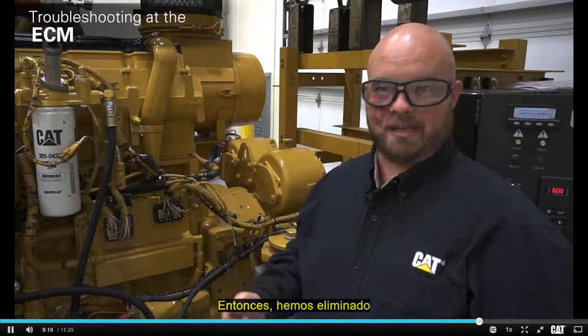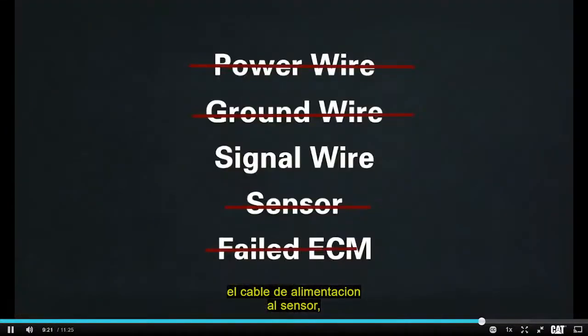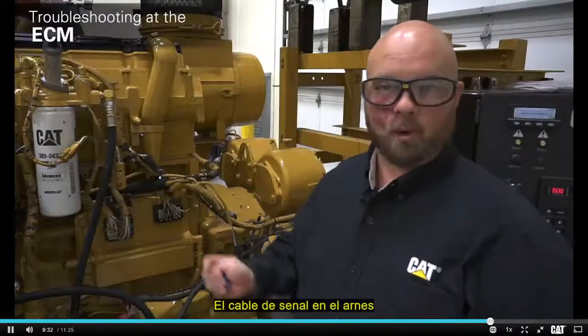So we've eliminated the power wire to the sensor, the ground wire to the sensor. The sensor itself is not at fault. Now we just validated the ECM is also working the way we expect it to, so what's left? At that point, the signal wire in the harness would be the root cause of the failure. Okay, so let's back up a step and change the scenario. I made the open circuit at my ECM, and again, I wait my debounce time.